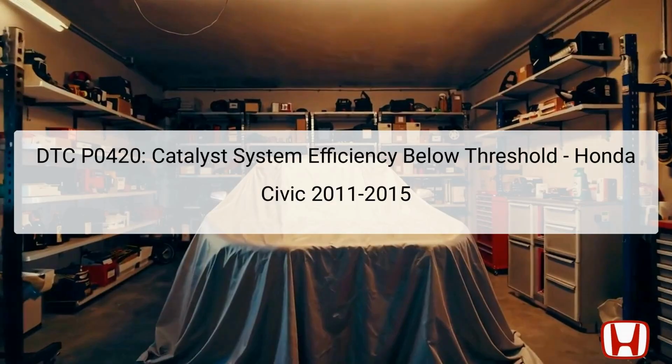The diagnostic trouble code DTC P0420 indicates that the catalyst system efficiency is below the designated threshold. This may be caused by insufficient conversion of harmful exhaust emissions, which can lead to potential problems with the vehicle's emission system. In a 2011 to 2015 Honda Civic, the primary components involved include the catalytic converter and the oxygen sensors, both upstream and downstream of the catalytic converter.